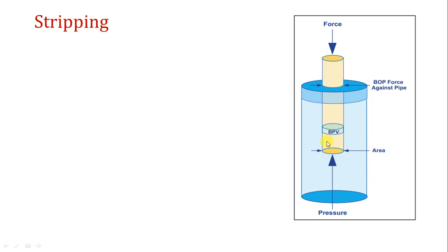Then you put something called an IBOP or internal BOP or back pressure valve. It is the same meaning. Then we open the full opening safety valve below it. Okay, so now we make the drill pipe secure and we run in hole with it slowly.